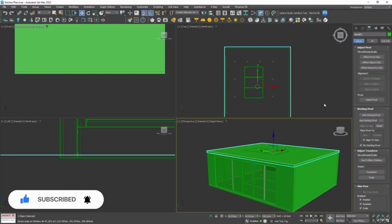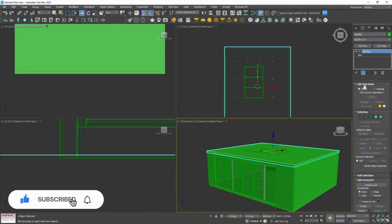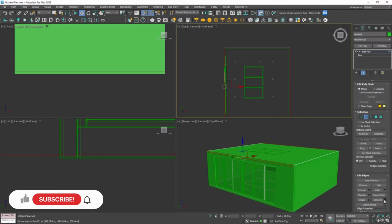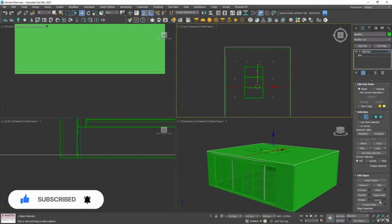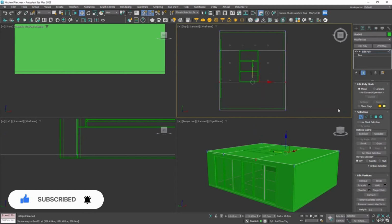So I'm going to select our ceiling, and back in the modifier tab, we'll add an Edit Poly. We'll select edges, and I'll just click and drag, select those, and then we want to connect them. So rather than hitting connect there, we'd only be able to create one connection. So if we click on the settings, let's make that 2, hit OK, select our verts, and then we're just going to snap those to the edges of our windows. And let's do the same again, but the other direction.